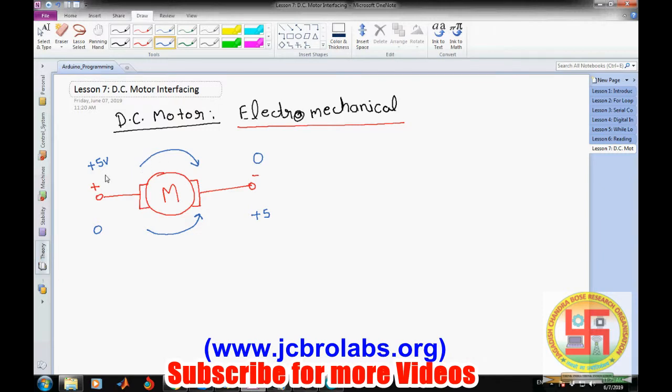That can only be tested by connecting the power supply. So that is a simple case: if we connect plus 5 here and 0 here, it will rotate in one direction, and if we change the polarity, it will rotate in the opposite direction. So in digital terms, plus 5 is regarded as 1 and 0 is regarded as 0. Now this is the working of a DC motor, very simple.